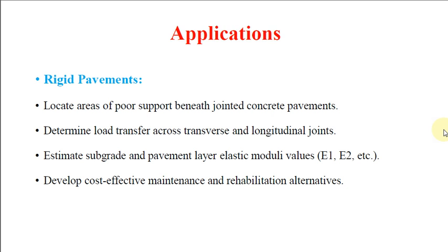The applications. Rigid pavements: locate areas of poor support beneath the jointed concrete pavements. Then determine load transfer across transverse and longitudinal joints. Estimate the subgrade and pavement layer elastic modulus values. Then develop cost-effective maintenance and rehabilitation alternatives.